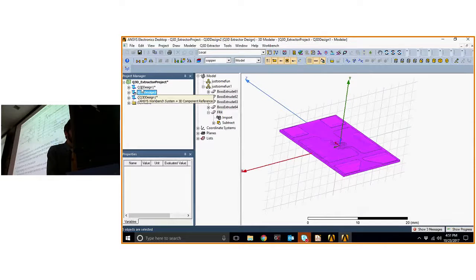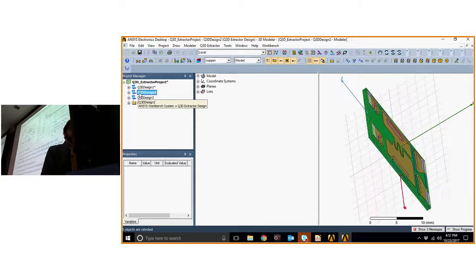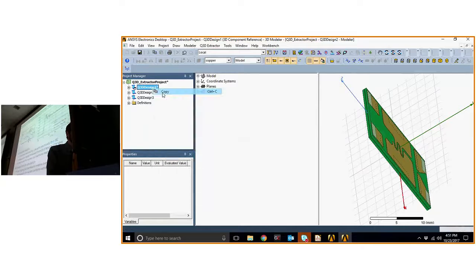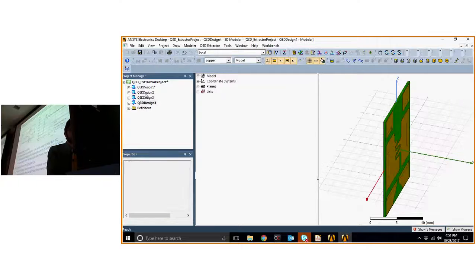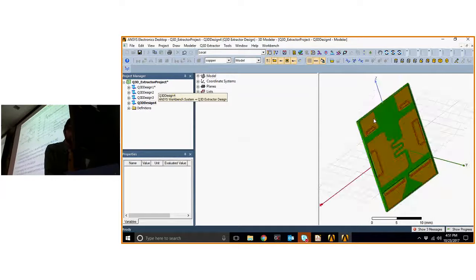a different project, I would recommend keeping the project that contains that design separate from the one you actually use. Because once you create the 3D component, it's internalized ANSYS stuff. You can't go back and edit it. You can only save over that again, at least in what I've seen. So keeping the source in its own file is a good idea. Making a separate file is just fine. I'm going to just duplicate that first project. I'll go ahead and